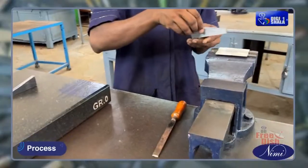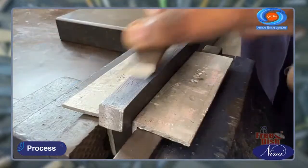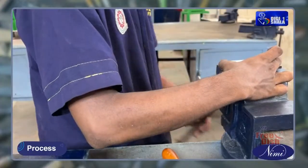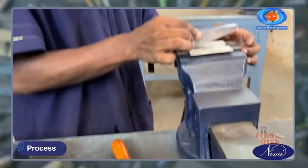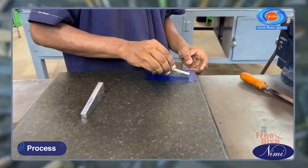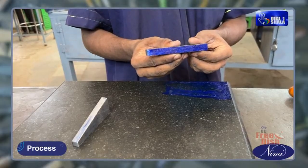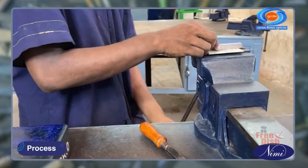Hold the job in a bench vise, scrape and remove the high spots with a flat scraper. Repeat the process until the Prussian blue covers the entire angular surface of part 1. Similarly, scrape part 2 and maintain the angular surface without high spots and at angle 19 degrees 17 minutes.